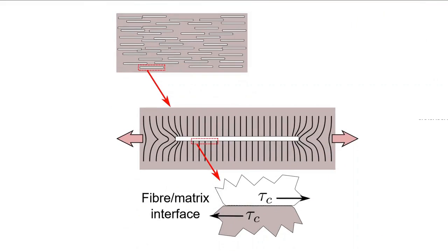If we look at a singular fiber in a composite reinforced by a long, continuous dispersed phase, then we have to consider the interface between the fiber and the matrix. For a composite which has a matrix which is less resilient than the reinforcing phase, pulling on the composite in the direction of the reinforcement will result in the matrix moving more than the dispersed phase. This therefore results in the interface between matrix and reinforcement being loaded in shear.